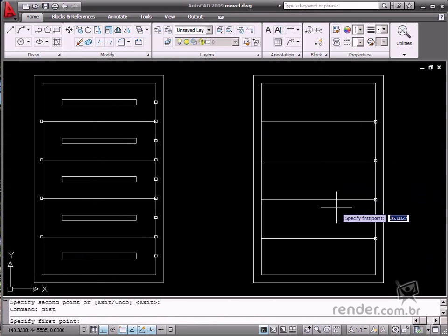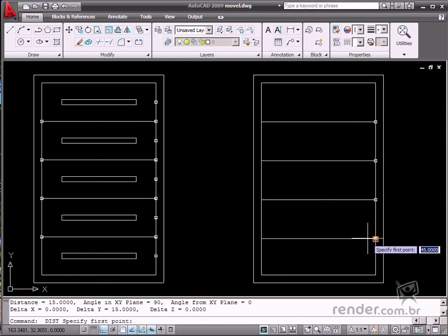Let's check the measurements and see the size of the last drawer is only 14 centimeters. Therefore, the division is not possible and you need to increase the size of the geometry to make equal part segments.